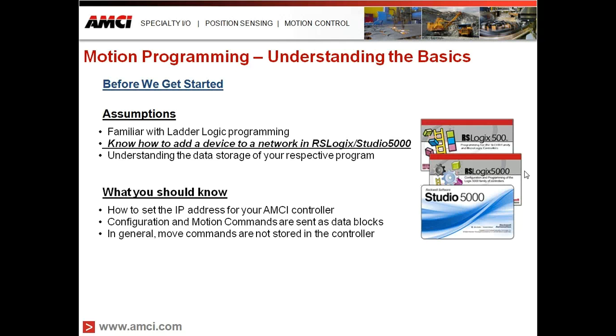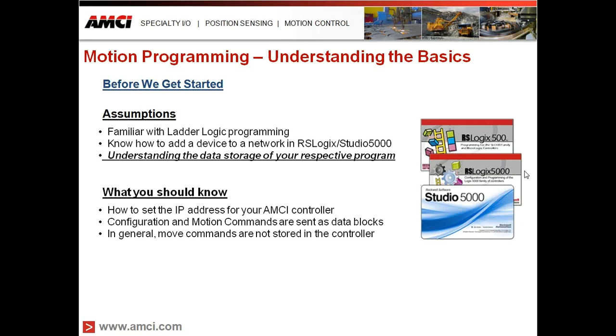And then you should also understand how the data is stored in your respective program. Whether we're talking about RSLogix 500, when we're doing that, we're talking about using the integer files. And when we're talking about Studio 5000, we're talking about using data tags.